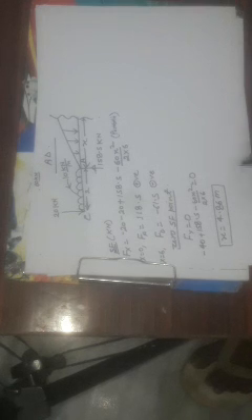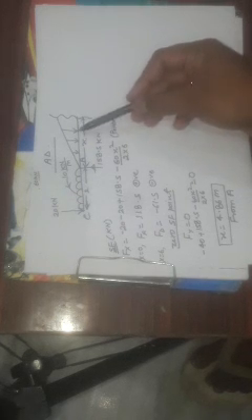When we calculate, we will find x equal to 4.86 meter. This value shows that at a distance of 4.86 meter from point A, the value of shear force is 0, or the shear force curve changes its sign. It is moving from the positive region to the negative region, right? Now